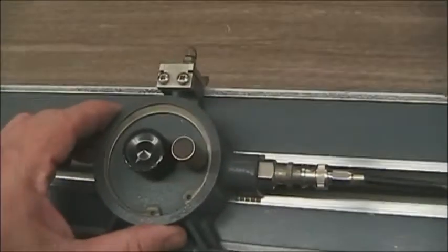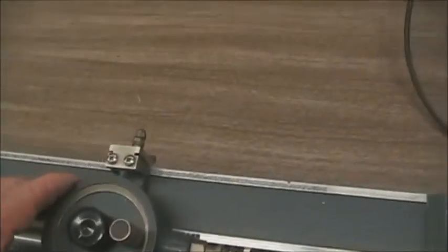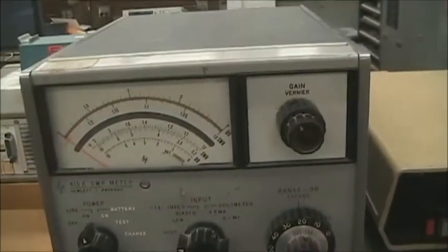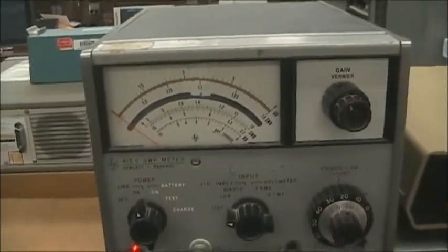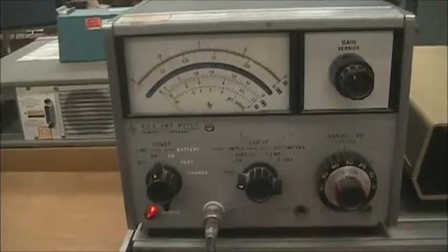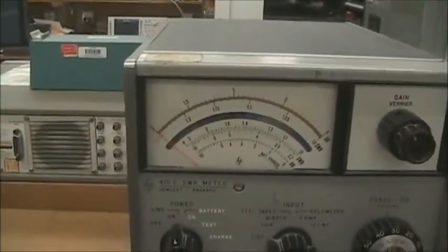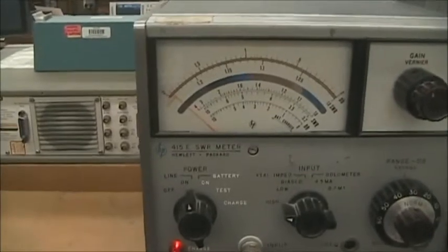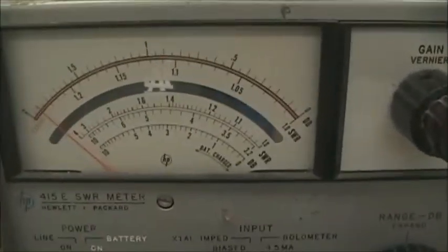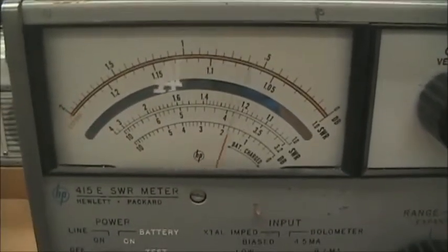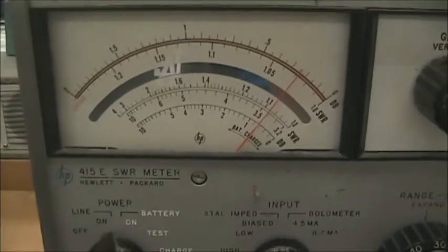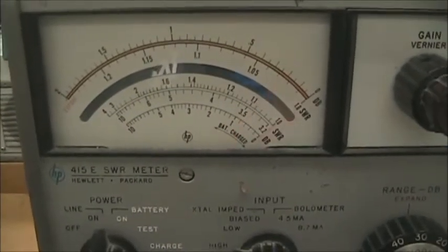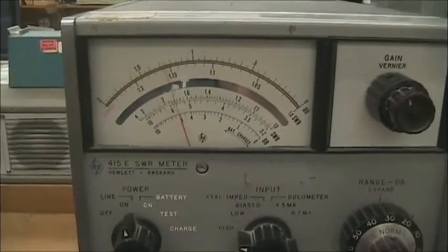So you have to move the probe. You've got to move the carriage to find the maximum signal. So as I move this along, it's a lower signal. I'm going to go down range here, see if I can see it a little bit better. Oh, there it's moving a little bit there. Let me retune the unit. A lot of manual tuning here. There, we got it. So that's the tuning of that bandpass filter to be exact maximum.